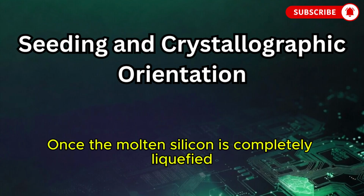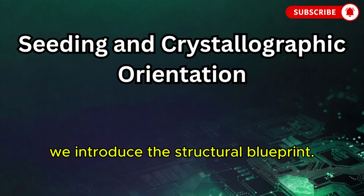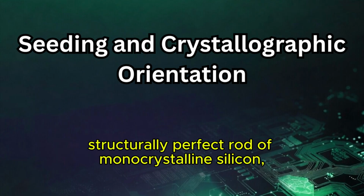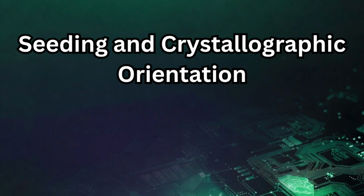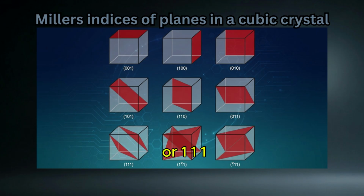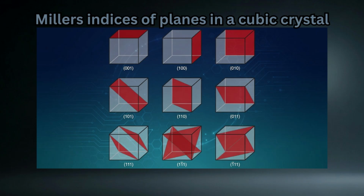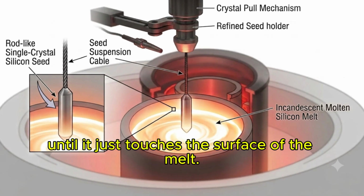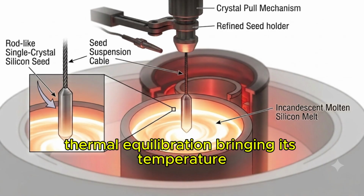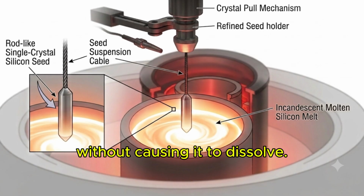Once the molten silicon is completely liquefied and thermally stabilized, we introduce the structural blueprint, the seed crystal. This is a small, structurally perfect rod of monocrystalline silicon, pre-oriented along a specific crystallographic axis, typically 100 or 111, depending on the desired electronic properties of the final wafers. The seed is lowered until it just touches the surface of the melt. It is held there momentarily to undergo thermal equilibration, bringing its temperature right up to its melting threshold without causing it to dissolve.